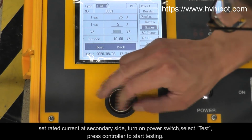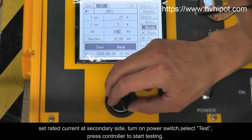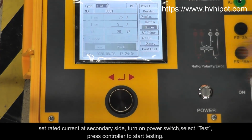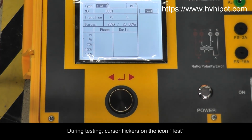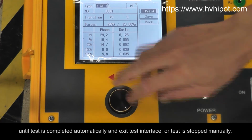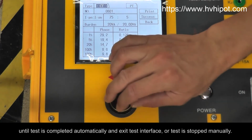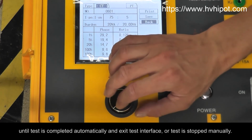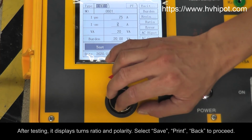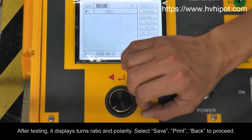Set rated current at secondary side, turn on power switch, select test, press controller to start testing. During testing, cursor flickers on the icon test, until test is completed automatically and exit test interface, or test is stopped manually. After testing, it displays turns ratio and polarity. Select Save Print, back to proceed.